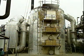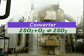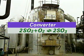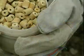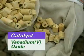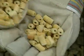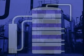In the converter, sulphur dioxide reacts with oxygen to produce sulphur trioxide. The reaction requires a catalyst, mainly of vanadium 5 oxide. This is most effective at 440 degrees Celsius. There are 4 beds of catalyst in the converter.